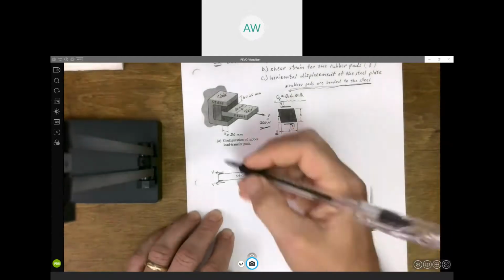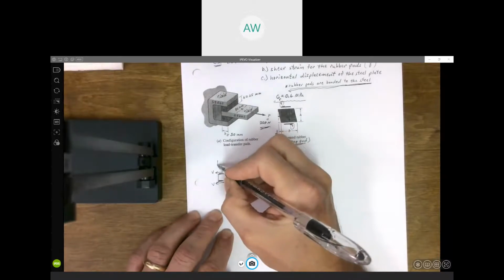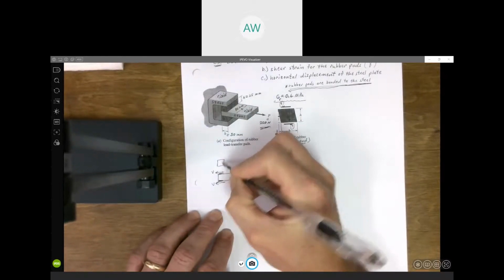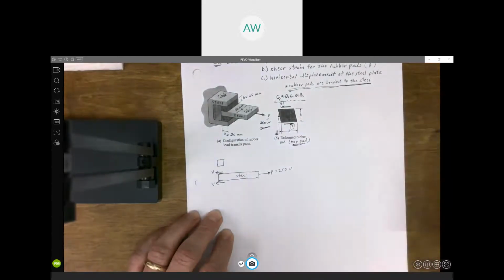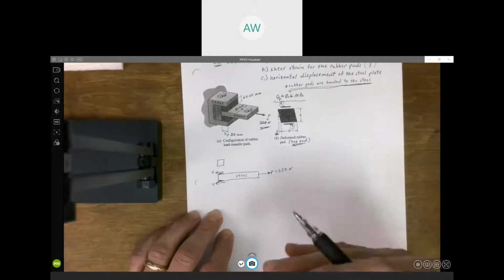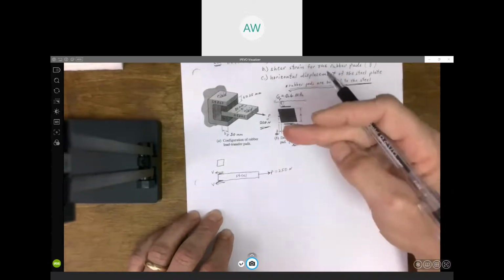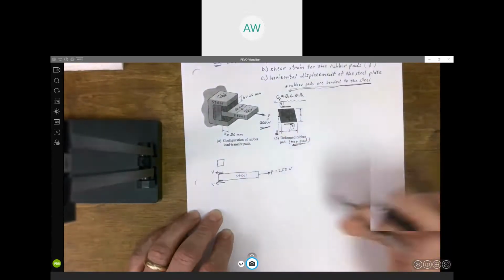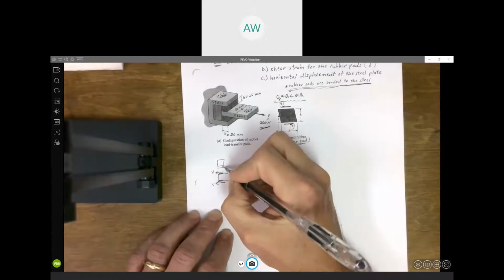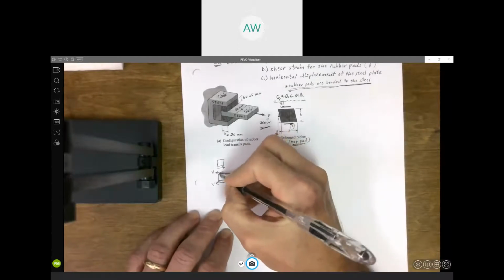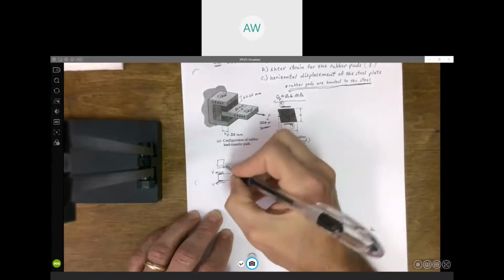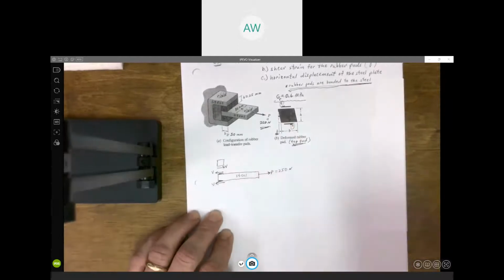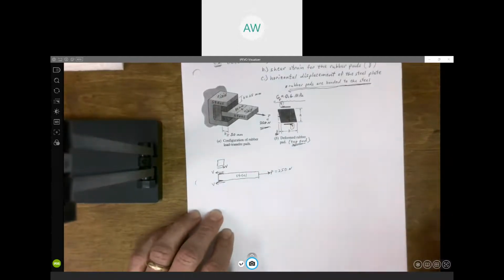Now, if you look at this, this is the cross section of that rubber pad. Again, equilibrium. When you draw free body diagrams, hopefully you learned this in statics. When you go from the free body diagram of one piece to the connecting piece, the force is the same magnitude in the opposite direction. So whatever that shear force V is acting on that glue on the steel plate, it's got to be the same as the shear force V acting in the opposite direction on the rubber pad.